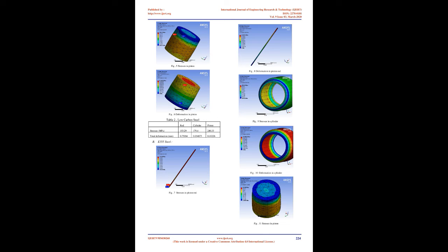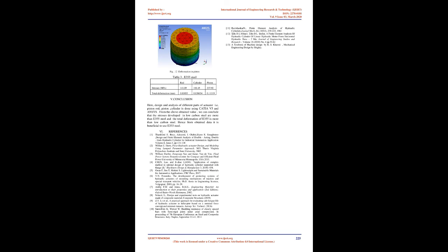Also the longitudinal stress is given by σL equals (P1R1² − P2R2²)/(R2² − R1²), where P1 equals internal pressure, 200*10^5 Pa, P2 equals external pressure, atmospheric pressure equals 1.0135*10^5 Pa, R1 equals internal radius, and R2 equals external radius.